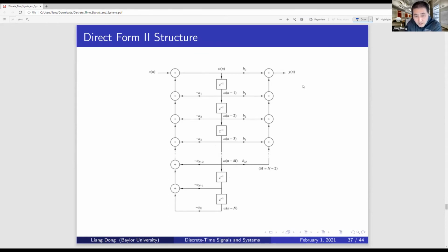So we have a block diagram, x[n] coming in. Now there is a feedback, so something needs to come back here, adding here with weight negative a1. This intermediate result, w[n], can go here. It is feed forward, connected here, with also a delayed version w[n minus 1], weighted by b1, and adding here, and so on and so forth.